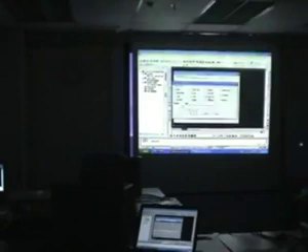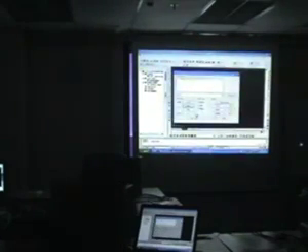I'm going to call out only the text values. That means only the text. If there are any lines or circles or blocks, they're going to be ignored. I only want to take the text. And from this text, we're going to create an XYZ text file.